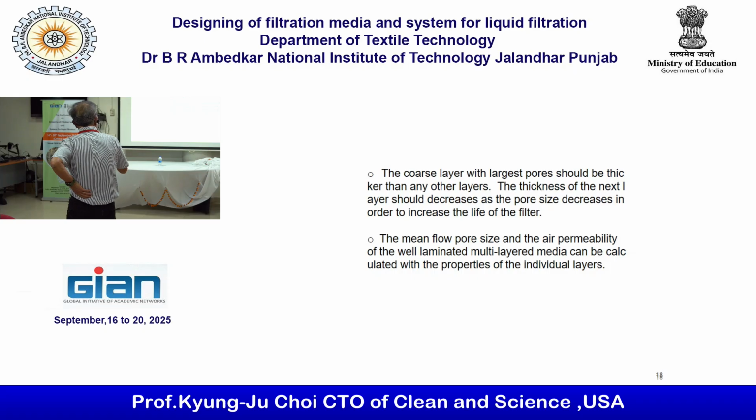Yesterday I actually modified everything, but somehow I couldn't find my file. But anyway, the thickness of the next layer should decrease as pore size decreases in order to increase the life of filters. So the mean flow pore size and the air permeability of well-laminated multilayer media can be calculated from the properties of the individual layers. That's the key point.